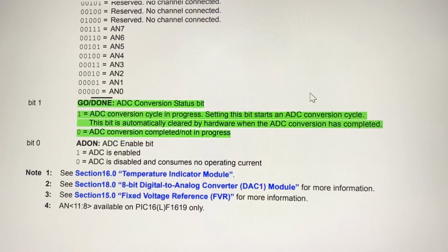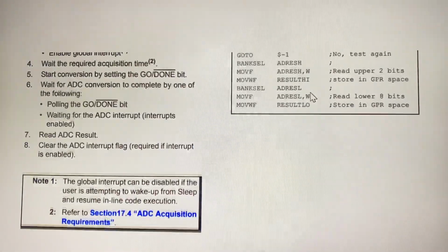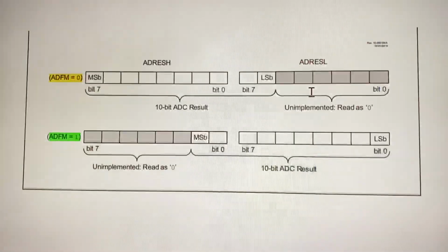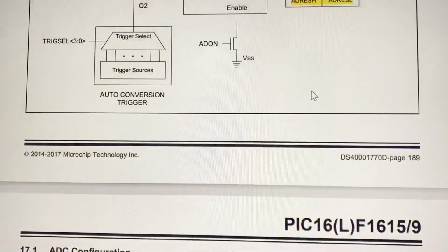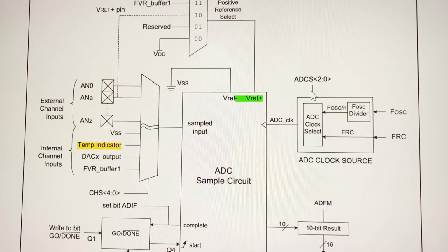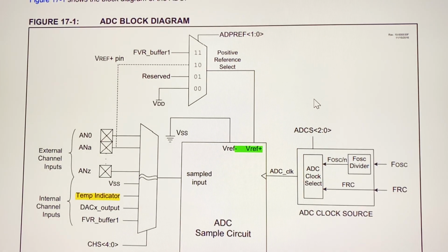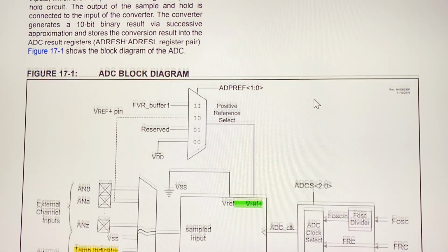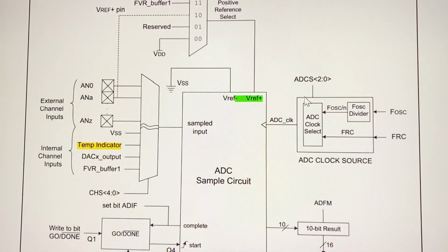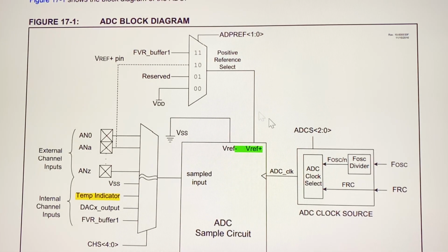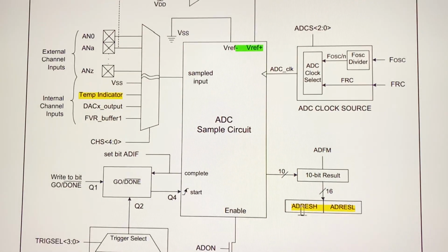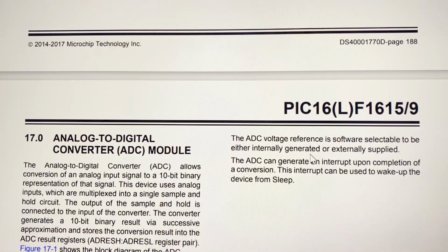Okay. So this lesson is complete with respect to the hardware architecture of the A to D converter. In my next lesson, I will explain how we can use software to take a voltage reading and transfer that reading from ADRESH and ADRESL to port C, so that we can see the reading.